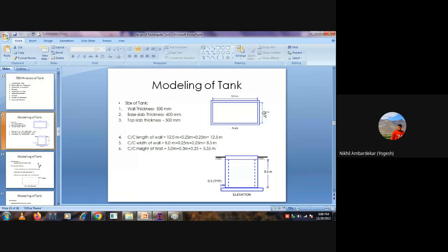So I calculated it as 23 mm. Okay, 23.61, correct, 23.61 mm. So that will be the maximum allowable deflection for the base slab. So we got this value. Then what is the next step? The next step will be to find the stiffness, the subgrade modulus.